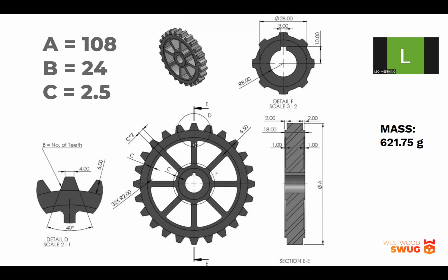So there's also different ways you can do this, you can either do there's a circular sketch pattern as well as circular extrude pattern. And I'll explain why I choose one over the other later on. But yeah, I will also be doing that for the teeth. But for now, we're gonna just do the pillars.